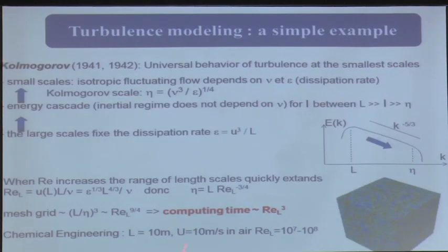The limitation of direct numerical simulation is related to the Reynolds number. You might be able to do the simulation, for example, in a pipe flow without any modeling up to Reynolds 10,000. The problem is, in the plant, it will not be 10,000, it will be 100,000, 1 million, maybe 10 million, and then you are facing that problem.